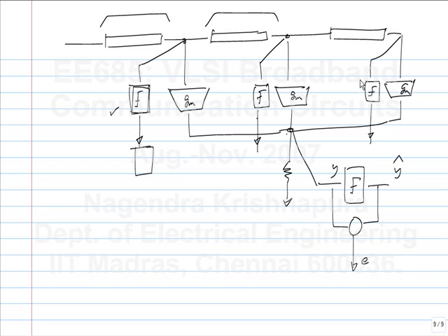Actually, this is a pretty complicated practical problem. The principle is very clear. There is no difference between this and anything else that we discussed. But so far, nobody has made a high-speed equalizer in which this LMS thing works properly without some other external aid. Usually you have to make some other measurements to get the whole thing to converge. It's not very easy to get this to converge.